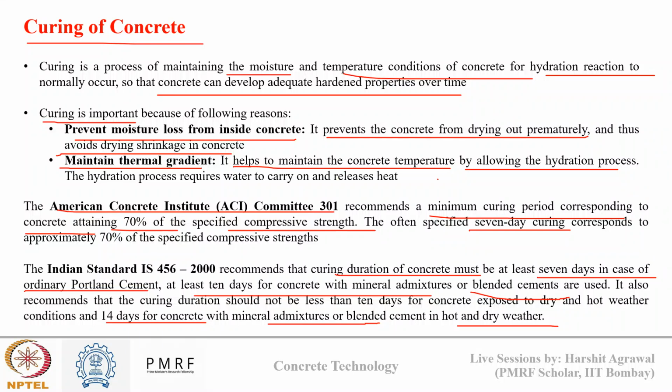Initially, when the cement hydrates, a lot of heat of hydration is generated inside my concrete. So if there is a lot of thermal gradient between inside and outside, then shrinkage can happen, which I don't want. I want to maintain the thermal gradient from the start up to a certain curing period, which is mentioned in different standards, which we need to maintain.